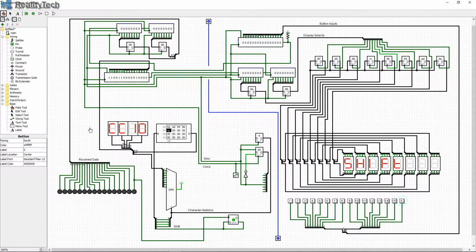If you think, there's a reasonable amount of work going on here and adding things to this. So you could use these to select programs. You could shift extra bits into the EEPROM to provide extra bits down here to provide you with feedback as to what's done. Again, you can use the latches to do that. You can get a fairly concise sort of operators panel without actually using a micro anywhere in here. This is all being driven by logic.